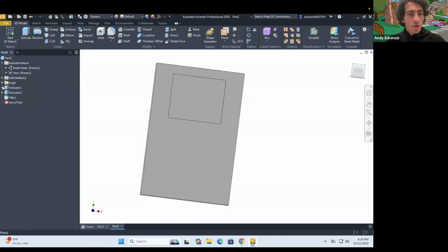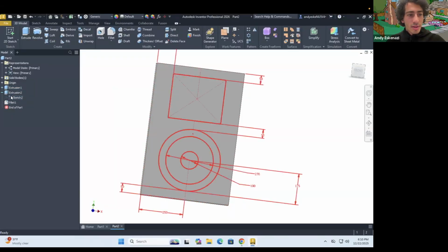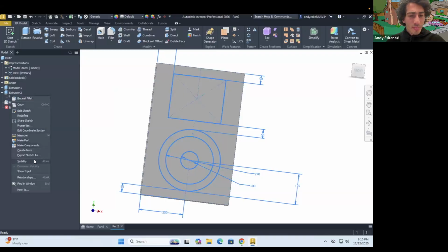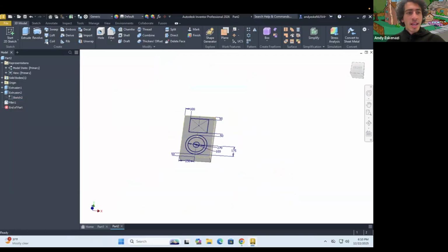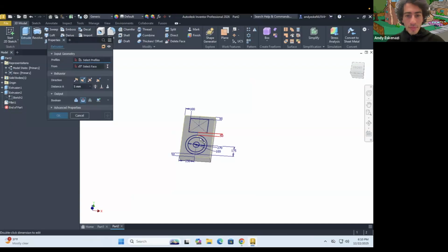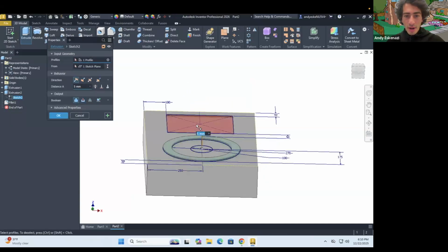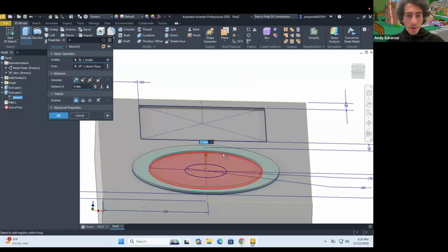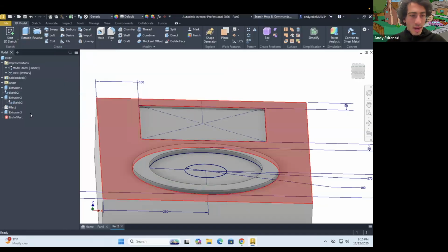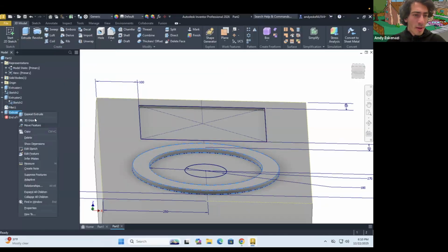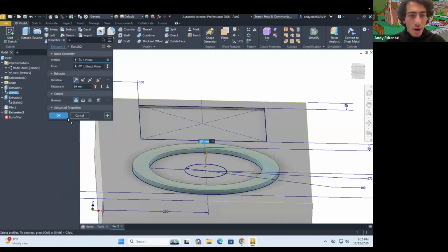But now, if we go here to actually extrusion 2, expand, I want to make this visible. I want to show these sketches. And the reason for that is because now I can go here to extrude. I can say, all right, I want to extrude now this area right here. And maybe this one we will extrude by 10. Actually, potentially more. Here, edit feature.